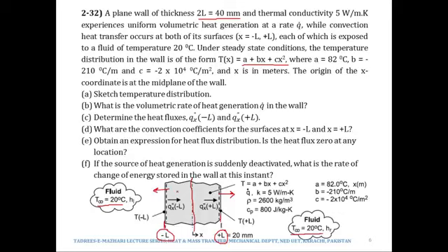Why will we use Fourier's law of heat conduction? The reason being that whatever heat is conducted till this face will be further transferred via convection to the fluid.